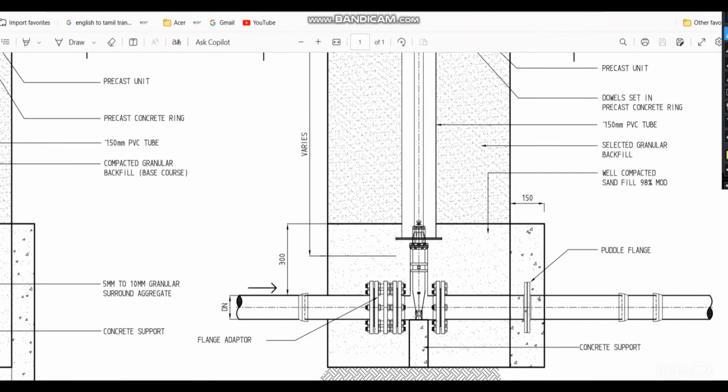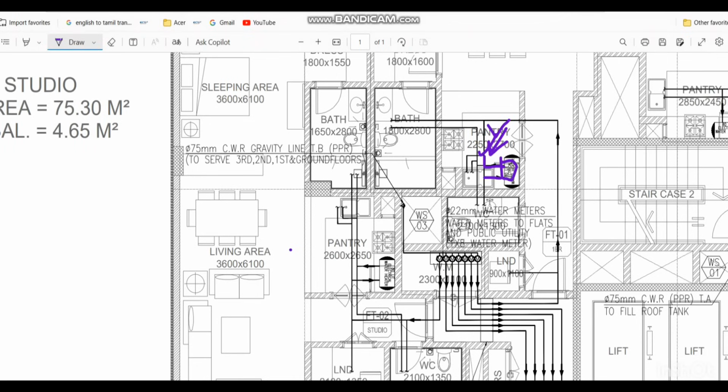So the valve itself has the arrangement like this. From the top you can directly connect the key to the valve and operate the valve. And here another important thing, like you see here, is this supply line which is going into the toilet. This further pipeline is not available so far, but what we have to do is provide one isolation valve at least, minimum, for one toilet. So for one toilet, a minimum of one isolation valve must be there.